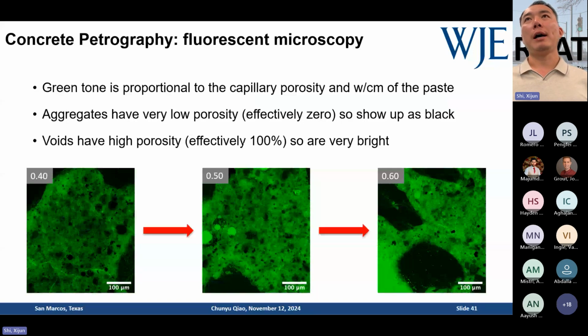That gives you a higher free water space at the beginning, and during hydration, the general hydration of the cementitious material, you have more capillary pores remaining in the higher water-cement ratio concrete, because you have a higher starting free water space. So just think about that.